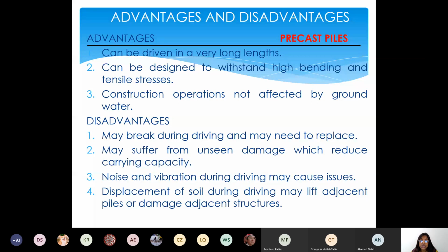All these struggles and challenges arise when you are constructing with loose soil, seashore construction, and construction of bridges across the river, right? There are chances of floating of the casings, at the same time erosion, right? Erosion of the abutment and the foundation. There are chances of removal of the pile cap itself. So you have to properly dewater and have proper scaffolding before you start pouring the concrete, and the time also has to be managed properly.